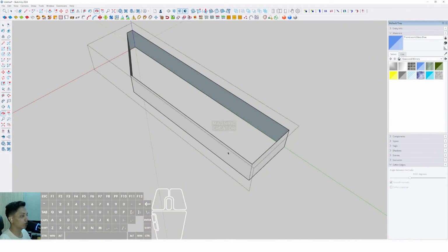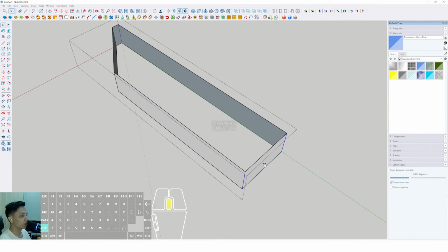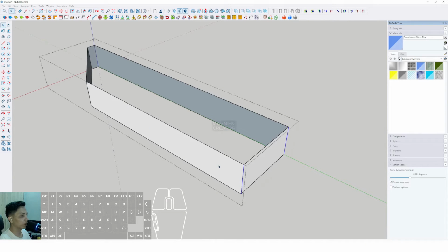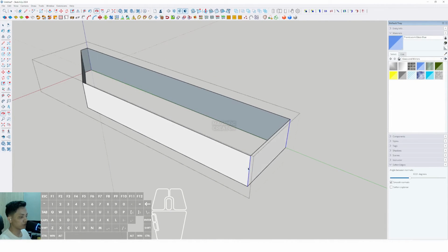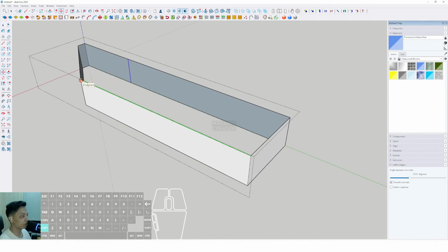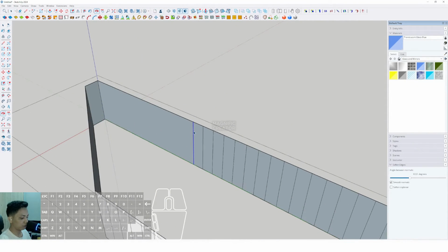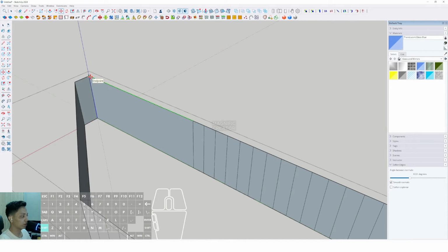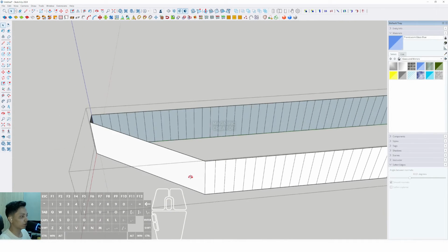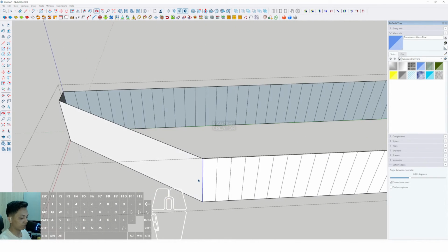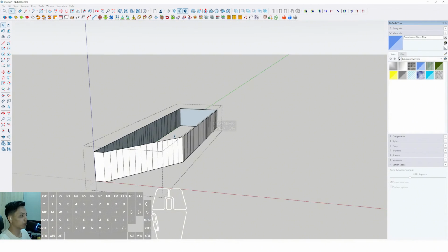We can do the same as the previous step to make the grid of the vertical schematic frame here. Then we can select both of these lines, select Move, press Ctrl and place them at this position, then type 30/ and enter. Also we can click this line, select Move, press Ctrl, place it at this position, and type 12/ and enter. Also this vertical line: select Move, press Ctrl, place it at this position, and type 14/ and enter, and it will be automatically arranged like this.